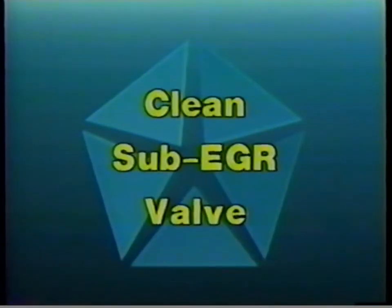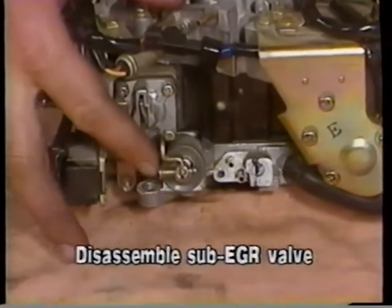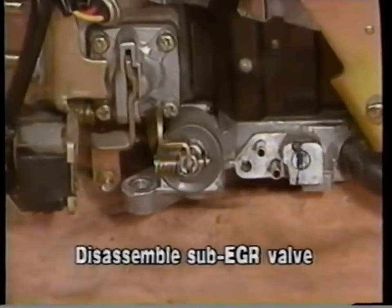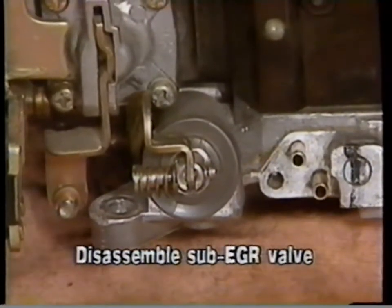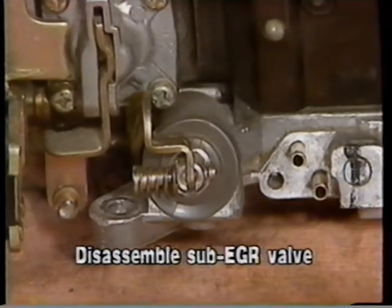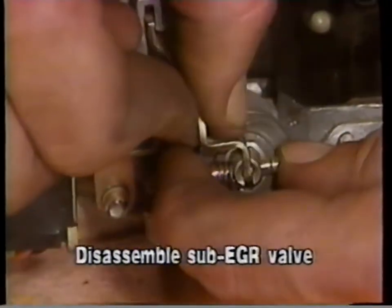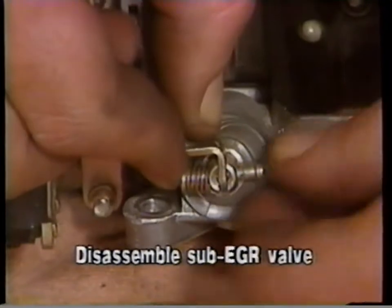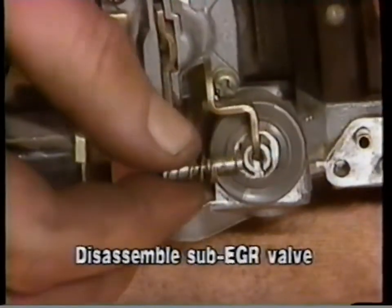The next part of this procedure involves cleaning the sub-EGR valve. To do this, locate the sub-EGR valve on the carburetor under the accelerator pump housing and disassemble the valve by first removing the E-clip from the pin connecting the plunger to the throttle linkage. Discard the E-clip, remove the pin, and separate the throttle linkage from the plunger, being careful not to lose the small steel ball and spring located in the end of the plunger.